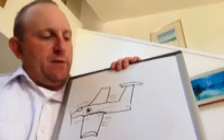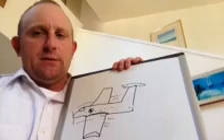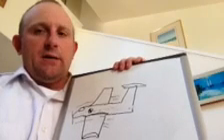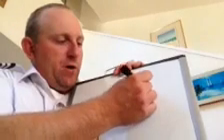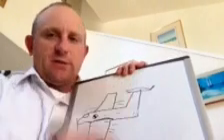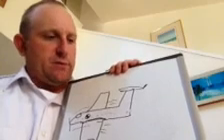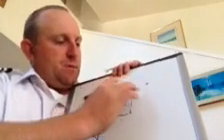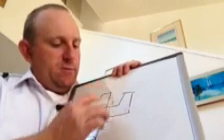The one thing that is a challenge with that is at low airspeeds, without that induced airflow, it's going to require more control input on our part to get the same desired results, since we've taken that out of the induced airflow area.